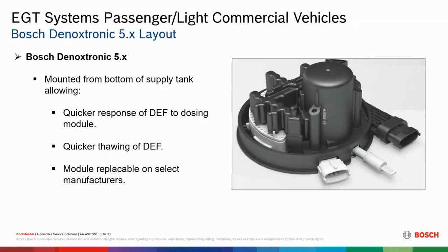It's got a quicker thawing time for the DEF fluid. So when we thaw it, the heat has got to turn on. We can thaw it right around the inlet port now, whereas before, everything's got to be thawed: the lines inside, the pump up at the top. So everything's got to work all together. So the time-wise takes longer with the 3.1 system. And there is time that's allowable by the EPA on any diesel when certain temperatures are there.